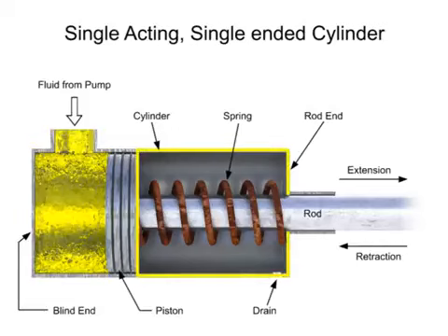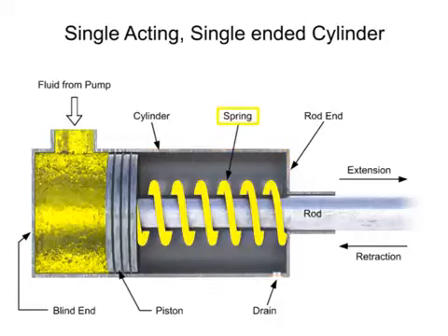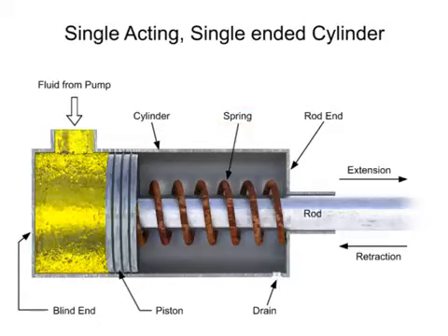The other side of the cylinder utilizes a mechanical load, springs, compressed air, other cylinders, or the momentum of a flywheel to push the piston back in the other direction. This particular cylinder utilizes a spring on the non-fluid side. A single-acting cylinder produces linear motion in one direction.